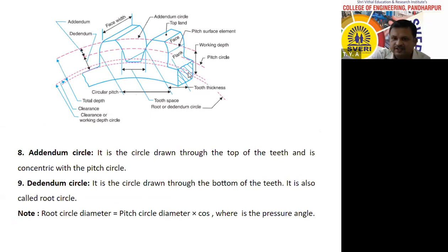Therefore, whenever two gears are in contact with each other, line contact is there, but this surface of the gear tooth becomes damaged after some years, maybe due to improper lubrication or this material of the gear or forces acting on the gear, or any foreign particle will come between the two surfaces of the gear and it will trap here.